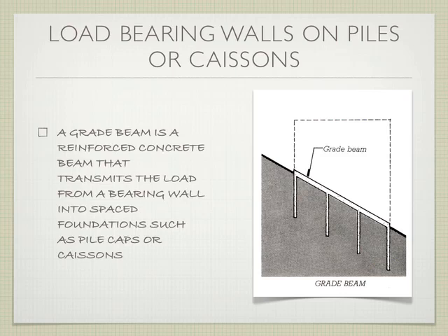We needed a way to support these buildings such that we wouldn't have differential settlement, right, which would cause the cracks and all the stuff that's historically in the 1960s buildings that are built downtown. This was for a multifamily 7-unit complex. And so we needed the ability to have a foundation so that the building could exist independent of that clay soil expanding and contracting, okay?